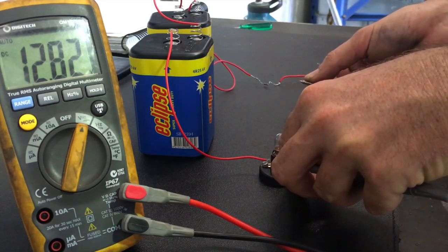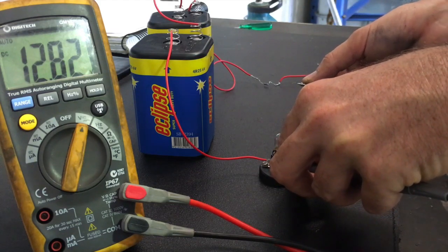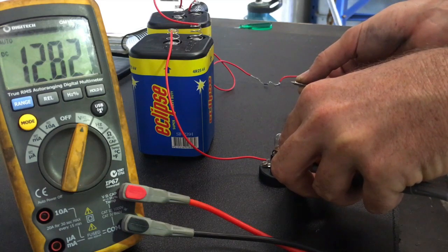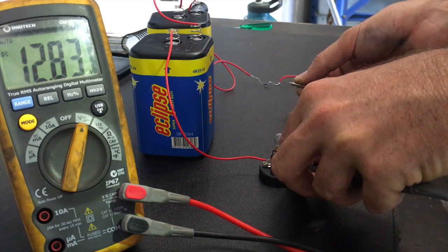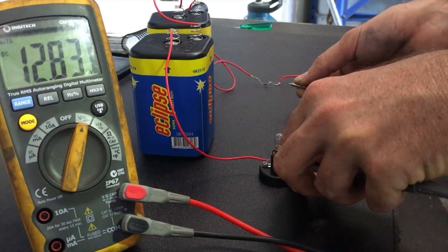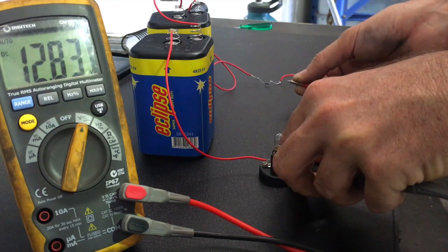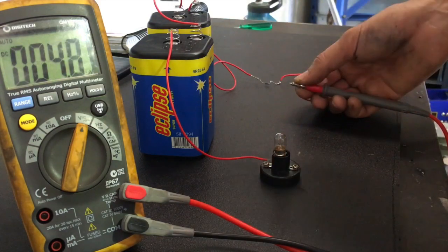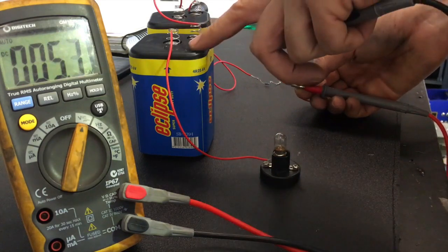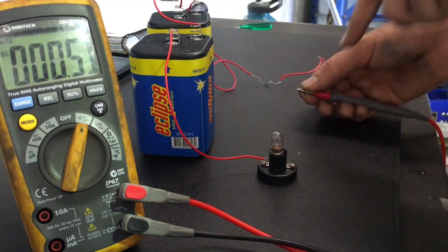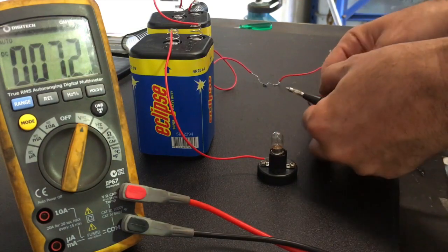So by separating the circuit like this, I give myself a false sense that, oh, hang on, 12.8 volts is flowing, so why isn't the light lighting up? And that is true, 12.8 volts doesn't flow. Voltage is a potential difference between the two terminals, and 12.8 volts, or whatever your battery voltage is, will always drop from one end of the circuit to the other end of the circuit. What that's not telling us is how much is getting used up by the various parts of the circuit.